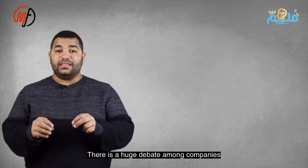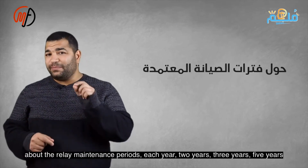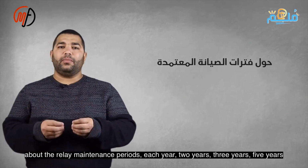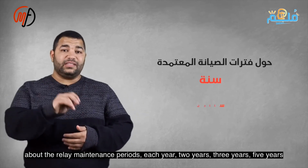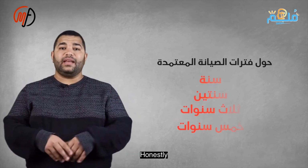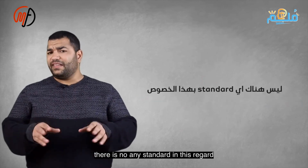There is a significant debate among companies regarding maintenance intervals, meaning how often should I perform maintenance on the relay? Every year, every 2 years, every 3, or every 5? Honestly, there is no standard regarding this. However, as an engineer, I prefer to conduct maintenance tests on the relay annually.